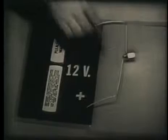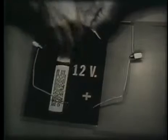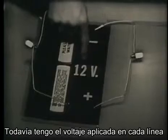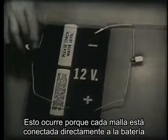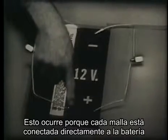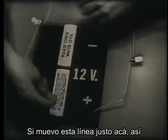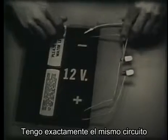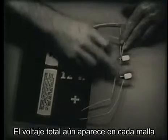Now, when the bulb is placed in this manner, it's pretty obvious that the applied voltage is across the bulb. If I place a second bulb over here, like this, it's obvious that I still have the applied voltage across each light. Now, this is because each of the branches is connected directly across the battery. If I move this light over here like this, I have exactly the same circuit. The total voltage still appears across each branch.